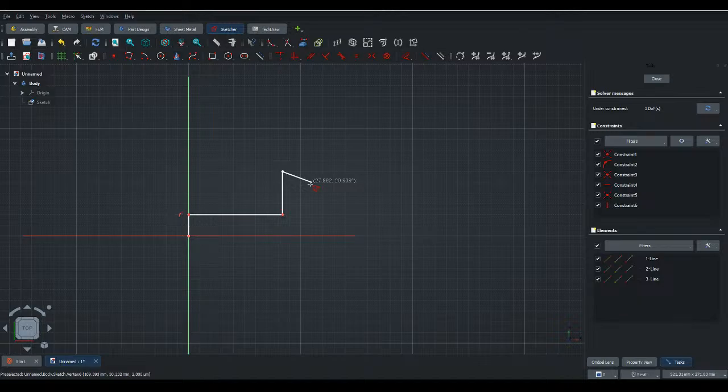Okay, so if you look at my cursor, it has the red symbol next to it. That tells me that I'm using the polyline tool. And then you'll see right now it's just the one red symbol. And then pay attention. When I get this line close to horizontal, it's snapped to horizontal, and then another little red line symbol popped up. Can you see that? Yeah, it's happening for me too. I'm making a vertical line right now. That's the symbol for horizontal. And if I get vertical, it gives me a vertical line. That's telling you that when I click to draw this line, it's going to give it either a vertical or a horizontal constraint. So meaning that line will be constrained vertical or horizontal.